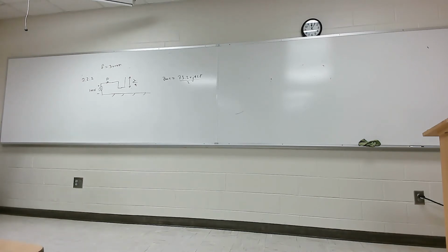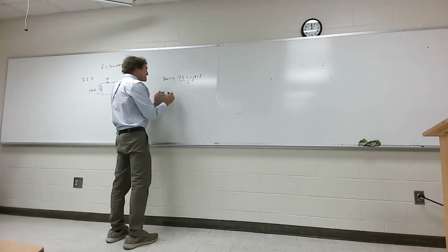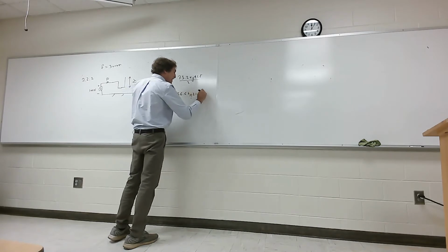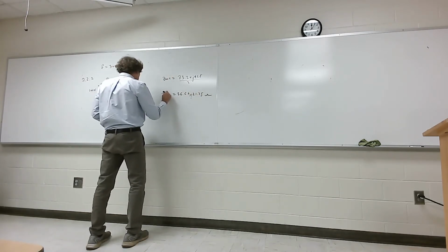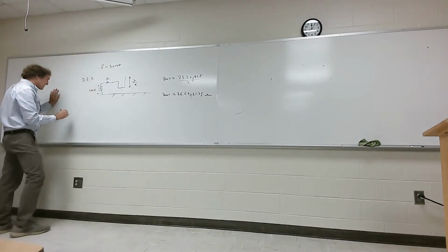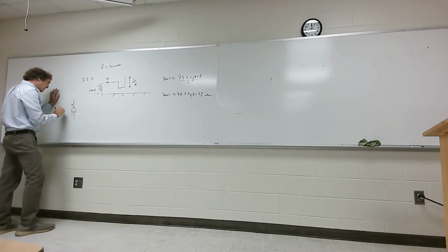Now, with that in mind, we can see, what is this exactly? So that's 36.6 plus J 21.25 ohms. That's your antenna impedance. So what we're going to do now, electrically, this circuit will look like plus or minus 100 volts, right?